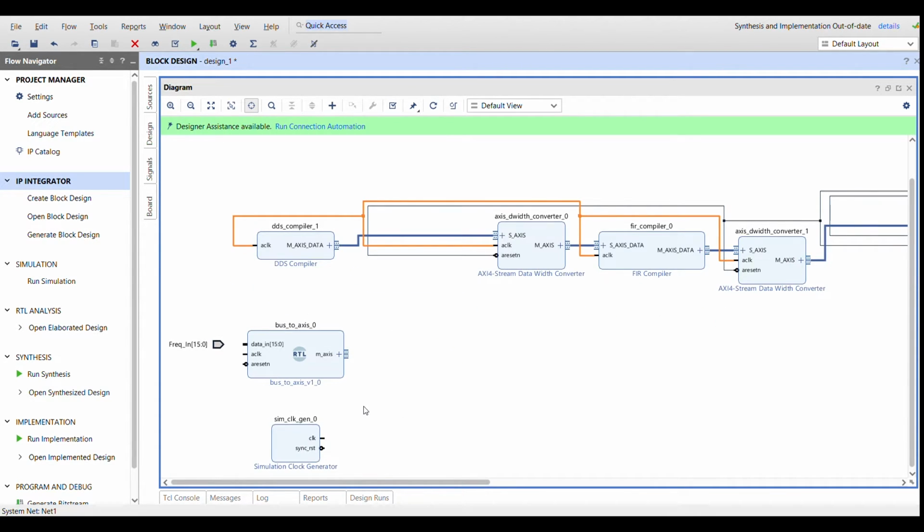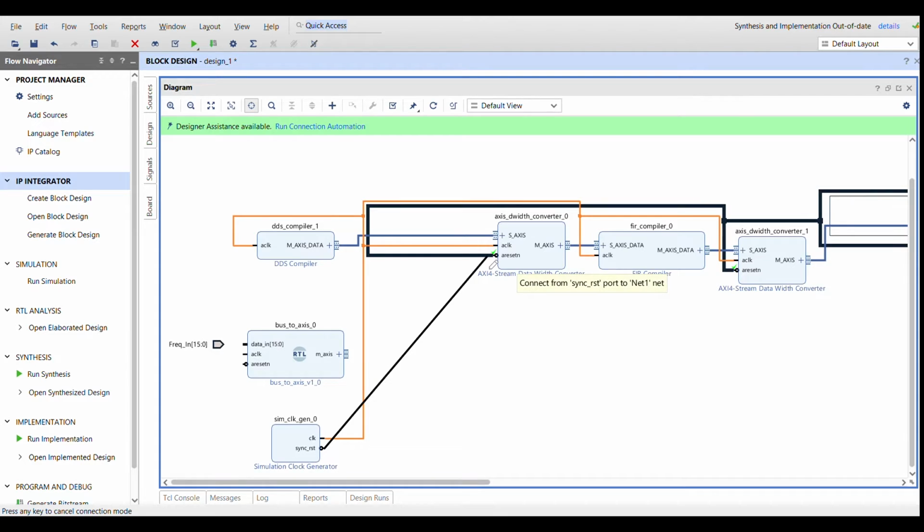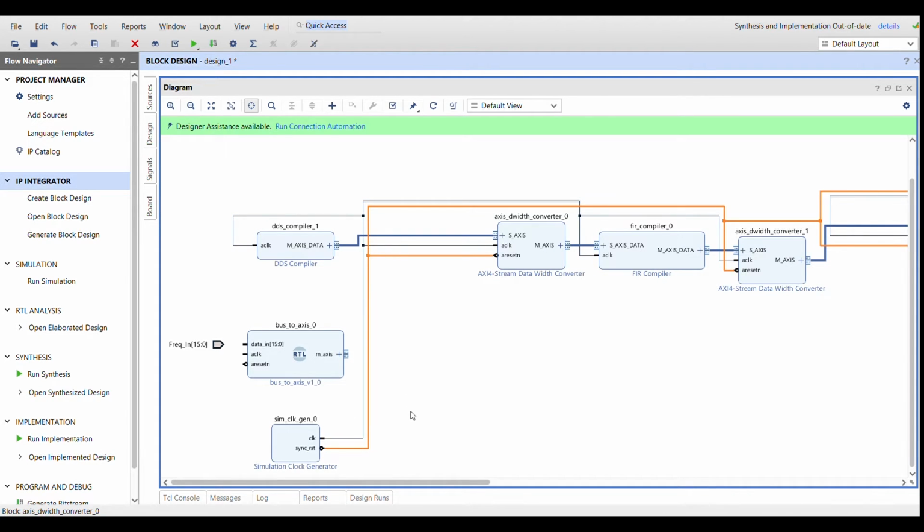We need to give clock and reset to everything, so there's a little bit of IP that generates a synthetic clock for simulations. No good for testing, it's only any good for simulation. That's set to give the right frequency and a reset width of 200 pulses.